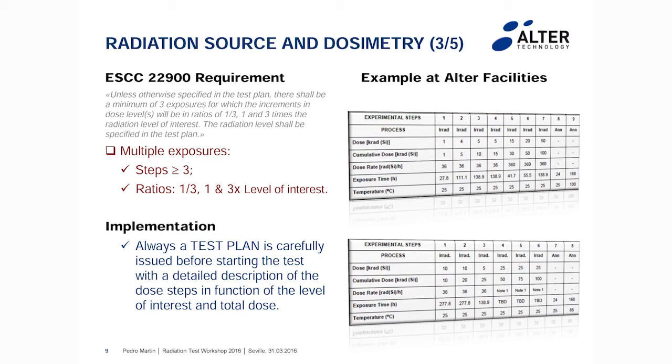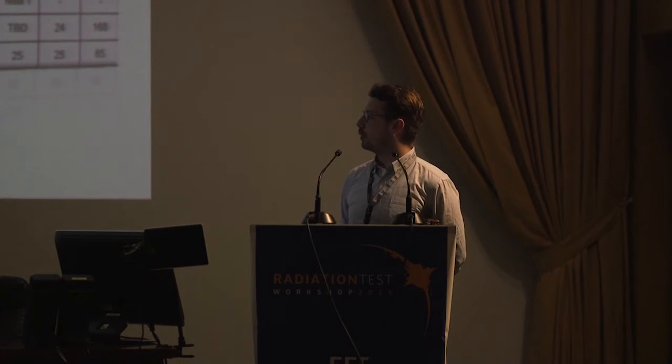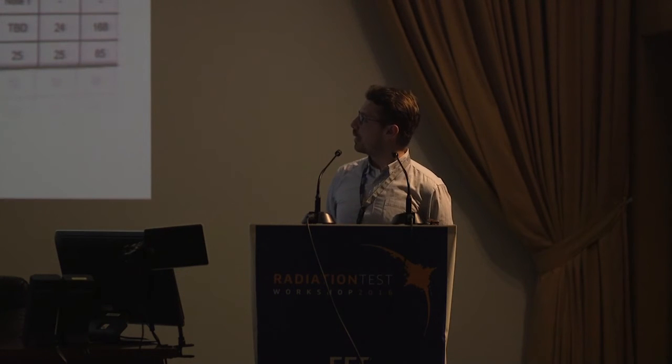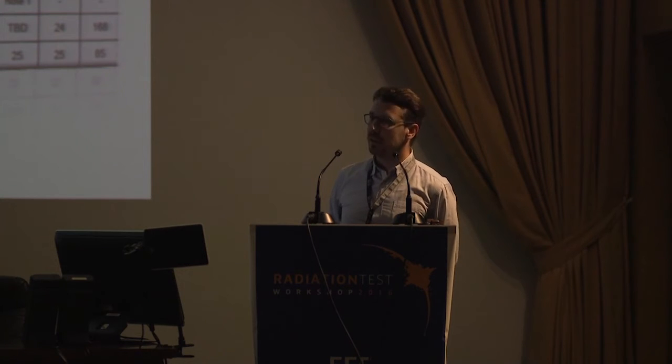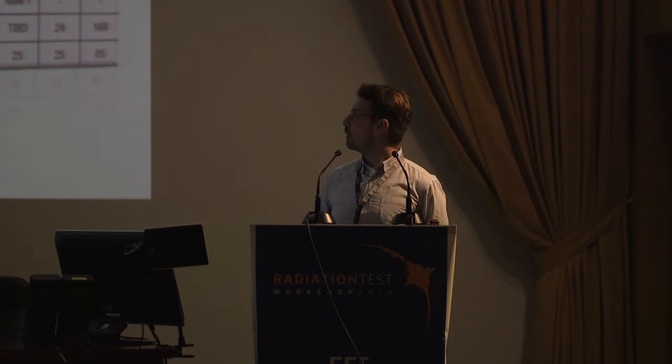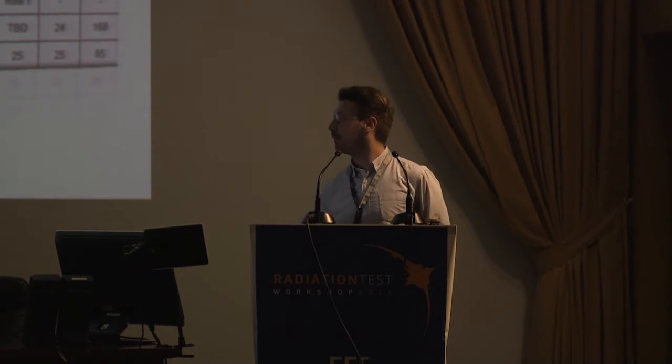In our case, we have experienced that, for example, for Solar Orbiter, we can change the dose rate during the test campaign in order to accommodate the dose levels agreed previously in the test plan to the results obtained. So this approach allows us to reduce the timelines and to get a better knowledge of the behavior of the device.